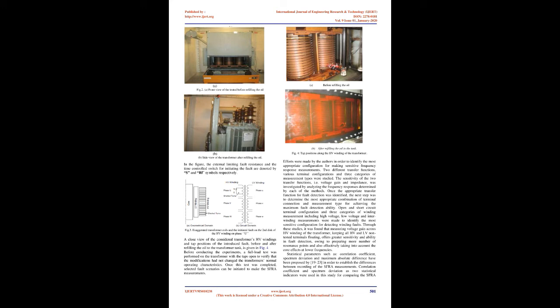The transformer tank and the lead ground shields were connected together to assure that no external impedance is measured and also reduce the effect of noise and the environmental effects. This measurement setup, accompanied by the experimental test object, completes the test setup for performing the SFRA measurements.